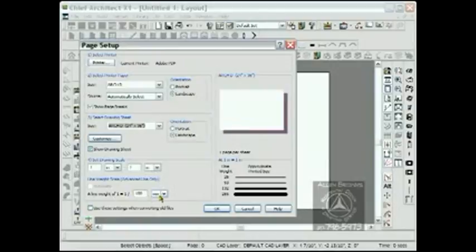Layout sheets in version 10 and before used 1/600th of an inch as their line weight scale. If you're bringing a layout over from version 10, you've got to change it to 1/100th of a millimeter. Otherwise, when you print it out, your line weights are going to be much too fat. The line weights now have been changed to more match the industry standard and closer to actual pencil lead sizes. Alright, now we're going to click OK.